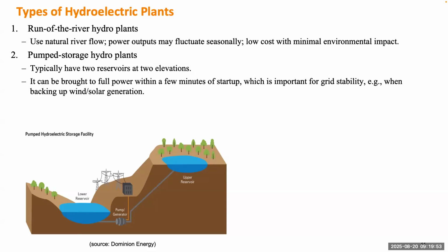The generator is a synchronous generator. It can operate as a generator if the rotor is leading the electromagnetic field, which means the mechanical torque drives the rotor to rotate ahead of the electromagnetic field, so it will generate electricity. You can also let the rotor lag behind the electromagnetic field, and that will consume electricity. We'll talk about that later when we get to the section on generator modeling. So the switch between generator and motor mode can be very simple. It only takes a few minutes.